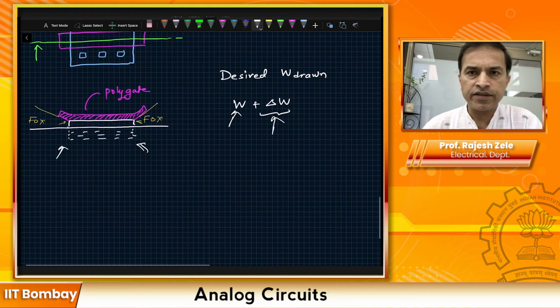So for example, let's say I have two transistors: M1, which is W by L, and M2, which is, let's use a generic number, N times W divided by L. So I have taken a transistor W by L and stretched the W to make it N times larger, N being an integer for the sake of this discussion.